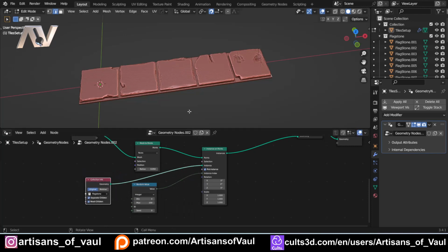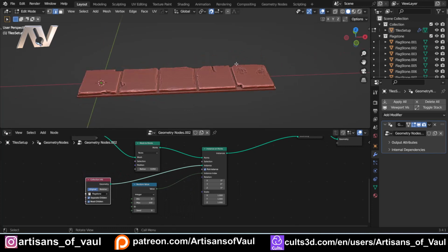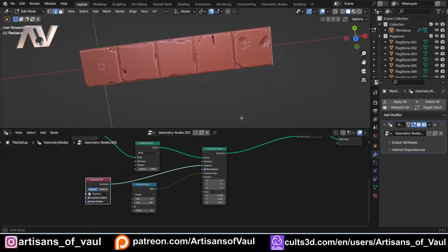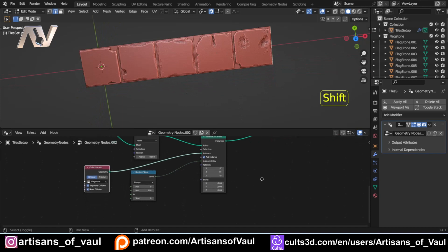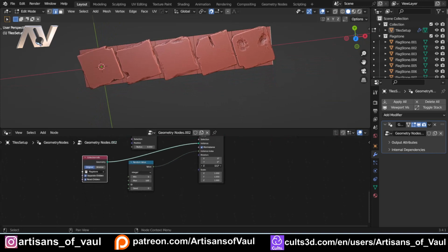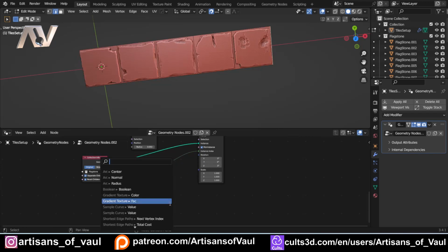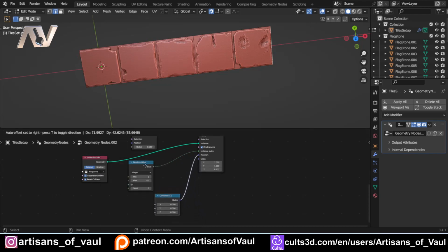Now we only want to rotate it along the x-axis, so basically rotating it round from the top down. So I don't need to control all of these, but you can notice I can do that. So we want to control this. Going to put that back to 0 and just drag that out. And to do that, we need a combine X, Y, and Z for vector. So that's going to allow us to do that because we can select only the Z axis.